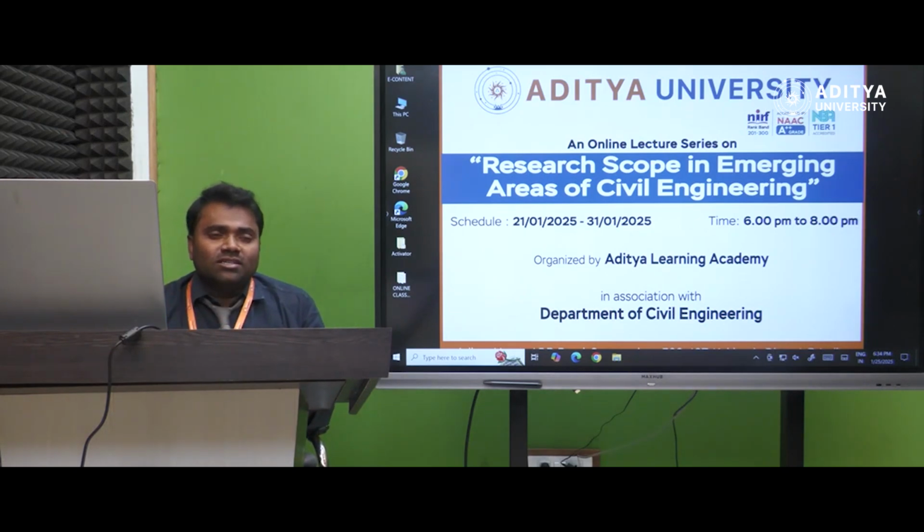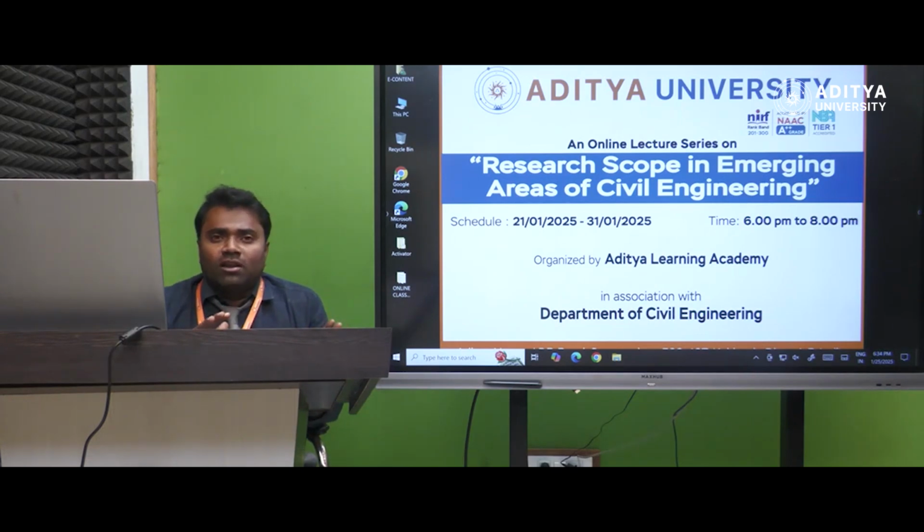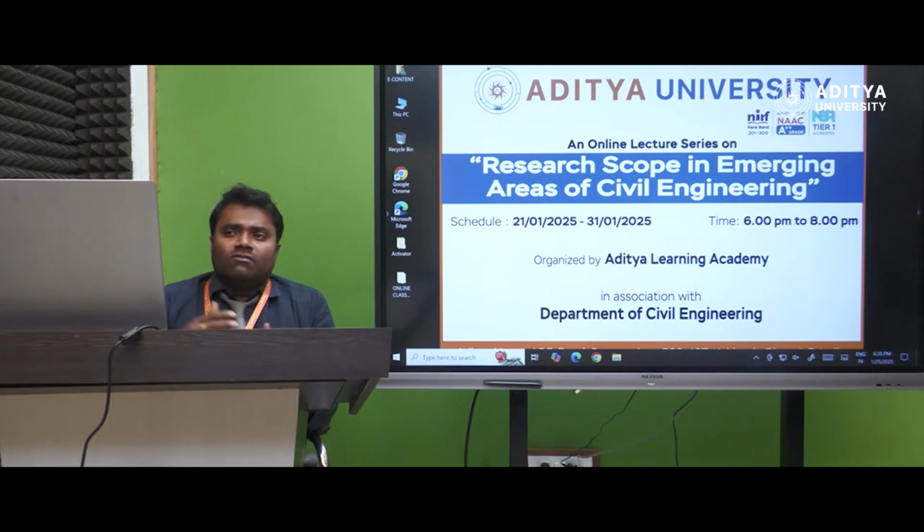So we have to prove that the inertial subrange slope should be minus 5 by 3. That is the validation part. With the help of this Kolmogorov scale, I validated that the inertial subrange has a slope of minus 5 by 3, and I communicated with a journal also, ISA Journal of Hydraulic Engineering.